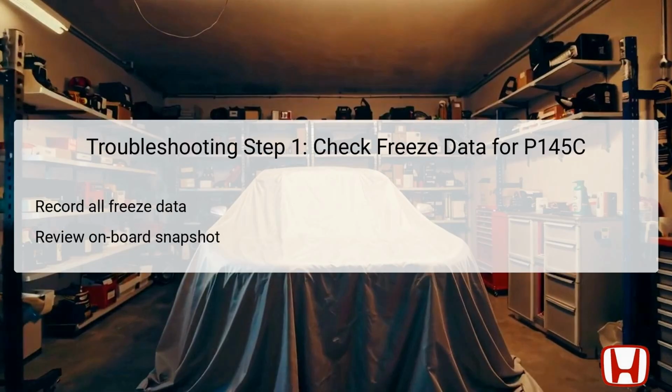The first troubleshooting step when addressing DTC P145C involves recording all freeze data and reviewing any onboard snapshot available. Freeze data captures the vehicle's operating conditions at the time the DTC was triggered, including variables such as engine temperature, vehicle speed, and battery voltage. This information provides valuable context that can guide the technician in narrowing down potential causes of the malfunction.